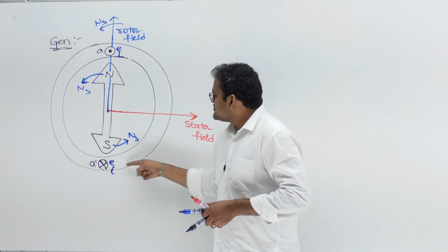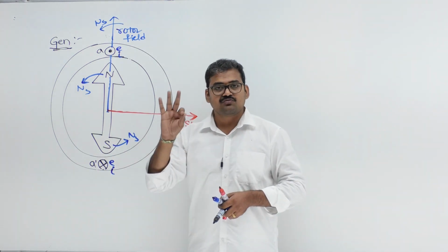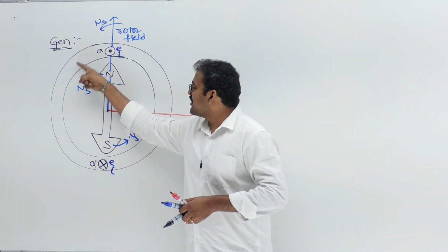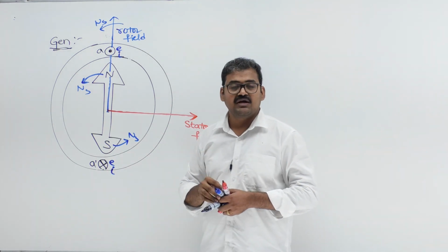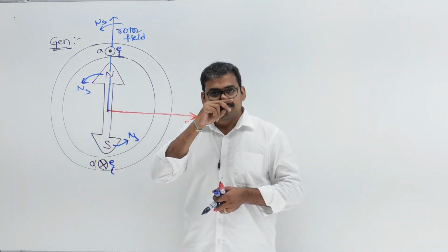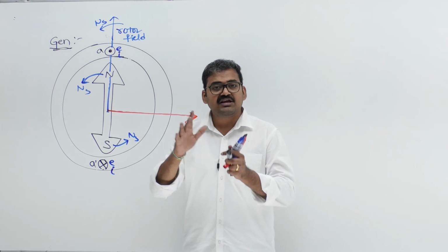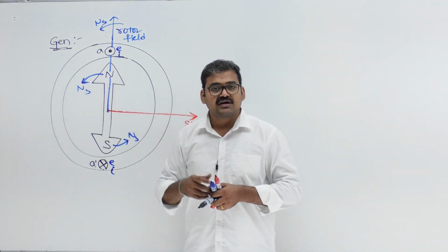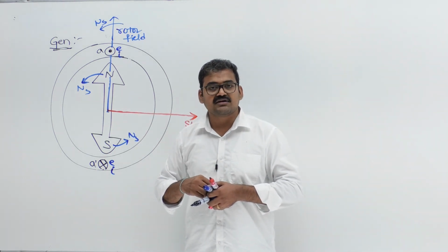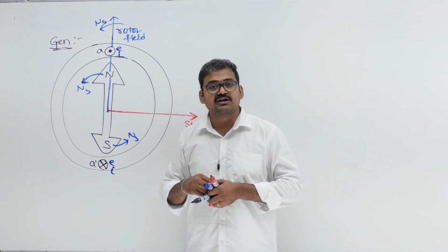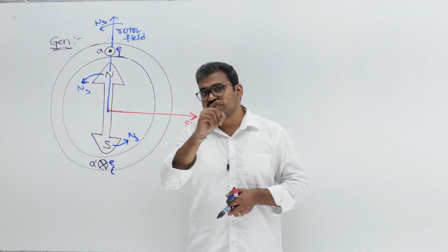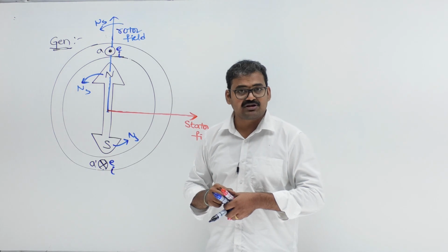Stator is a single phase winding or three phase winding? We will use three phase winding in armature circuit of synchronous machine. That too distributed winding. Yes, we studied. Whenever a balanced distributed winding is carrying balanced current, it will create a stationary magnetic field or rotating magnetic field? Rotating magnetic field. You remember that point? Yes.